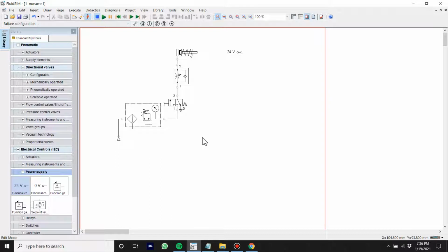You don't know this, so I need to tell you. In industry, so much is controlled by DC 24 volts. Sure, there's AC 110 and 240 and three phase, but 99% of stuff that goes into a PLC, which is your brains behind everything, is going to be 24 volts, and you should be happy because you're not going to get electrocuted by it. Okay, that doesn't mean you don't need to be careful around it, but 24 volts is going to be your electrical control.